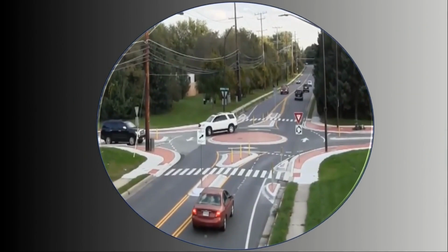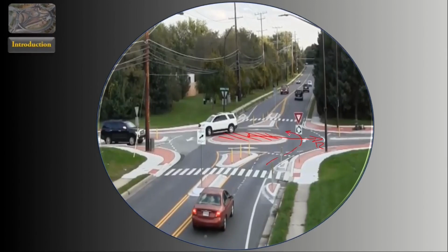Many mini roundabouts have a distinguishing feature. The center island is fully traversable. And of course, that's for a reason. Many mini roundabouts are so small in size that they can't accommodate the whole width of large vehicles inside their circulatory roadway, and the rear wheel path of large vehicles, or sometimes the whole path of larger vehicles, has to encroach on the center island.